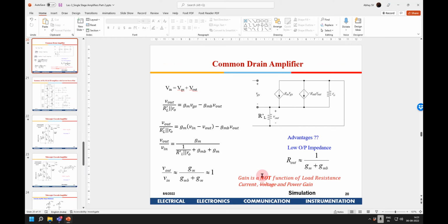My question is, the output is a multiple of your first stage and second stage gains, right? Because you have used a common source and a common drain. Correct. It means that it's just two stages of amplifiers we used for the design. And then what is the use of the second stage input transistors here? It's acting as resistors.